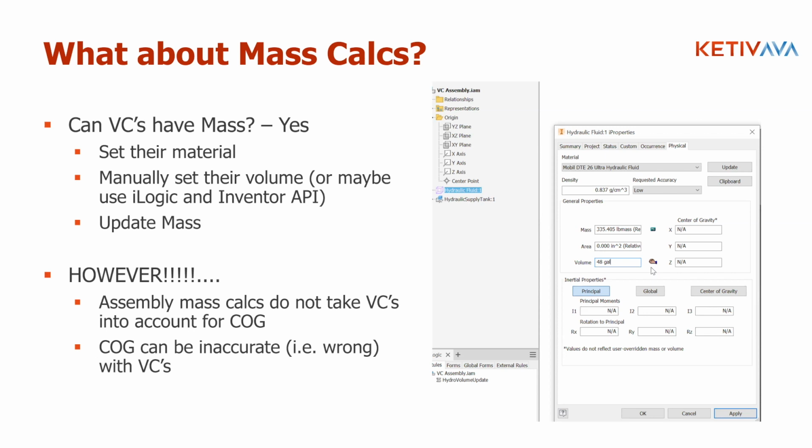Okay. So we had a question come in from Will about using transient geometry. No, it won't take, if I remember correctly, and I could be wrong on this because I've never really looked at it closely, I do not believe ASM takes transient geometry into account for mass calcs. It only takes into account actual resultant solid bodies. Okay. So even sketchwork isn't going to be considered a geometry-based feature inside of Inventor. It's got to be like a parametric solid.